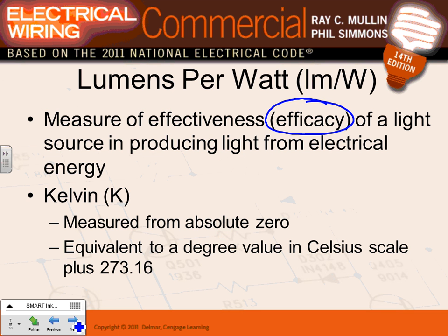Because of the energy code, Jeff, every fixture has a value called efficacy. How many lumens per watt can this fixture get? 20 lumens per watt or 100 lumens per watt? Andrew, I'm not going to tell you something you don't know. If you have a fixture that can throw 100 lumens per watt, that's much more efficient than a fixture that draws 10 lumens per watt, right?